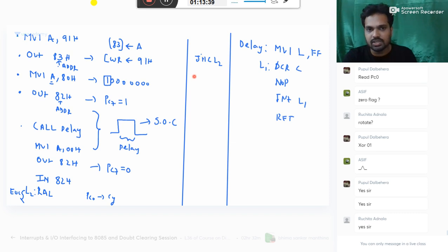So the conversion is completed. Then what to do is, please listen here. IN 80 hexadecimal, where you have port A. Now your accumulator got the data. Then what to do is OUT 81 hexadecimal.